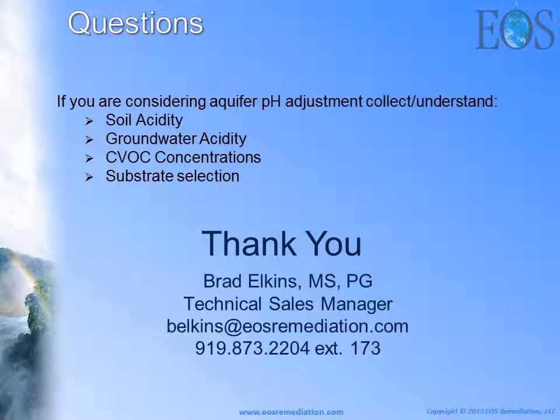The next thing is obviously the substrate you select, the organic substrate that you pick. If you choose something like EOS, it's a soybean oil based product, so you're going to get relatively low acidity. But if you choose to go with something that's more soluble like sodium lactate or molasses, just understand that when that material ferments, it ferments very rapidly and is going to release acids very rapidly, and that could be a problem for the system.